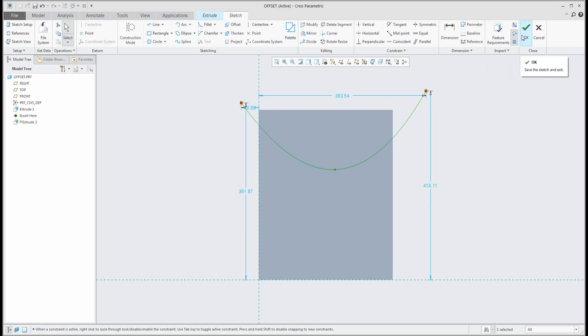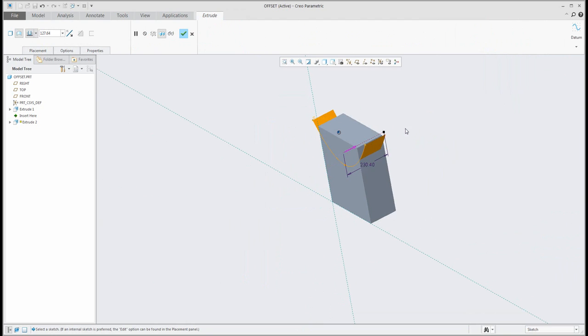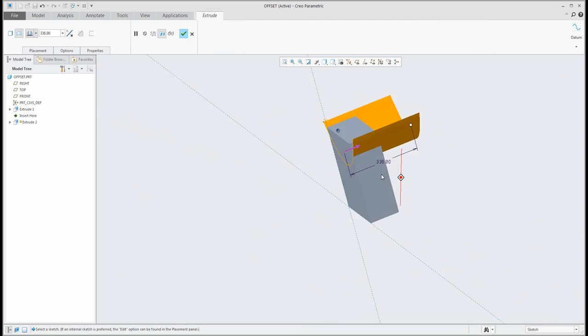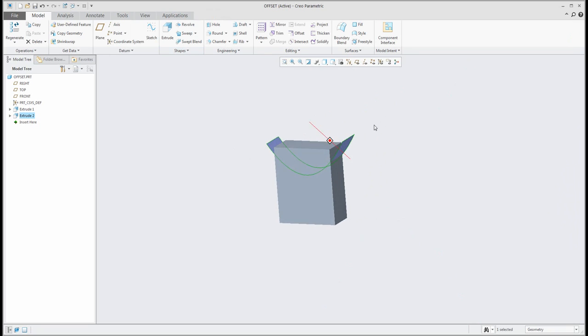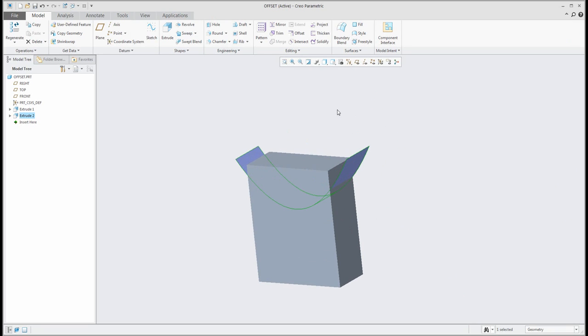This spline will create the surface for me, and based on that surface you can use the shift key and the system will automatically snap the selected edge or surface. I know that you know, but I'd like to show you one more time in case you watch my video tutorial the first time. And if you like this function, have a look at my old video tutorials and you will learn more about every feature with Creo Parametric.